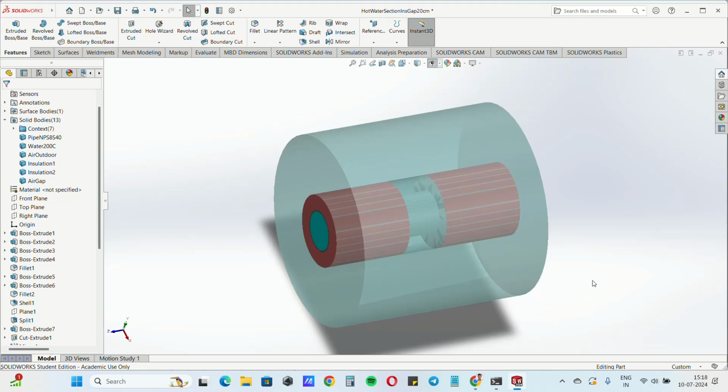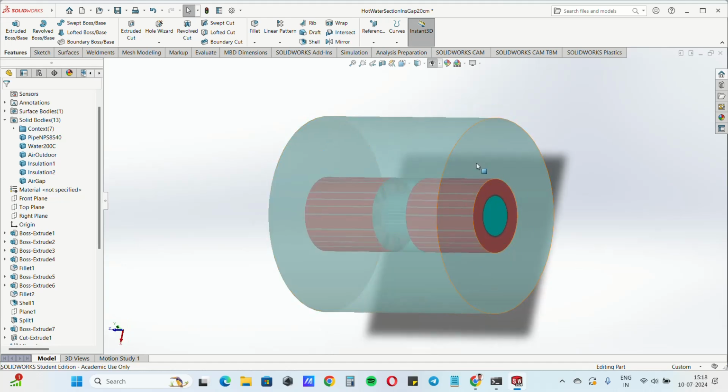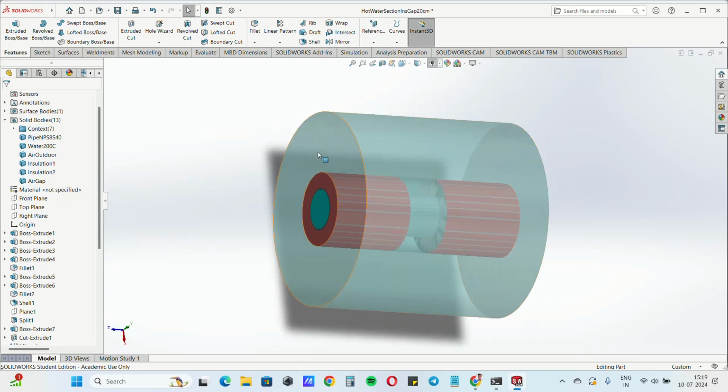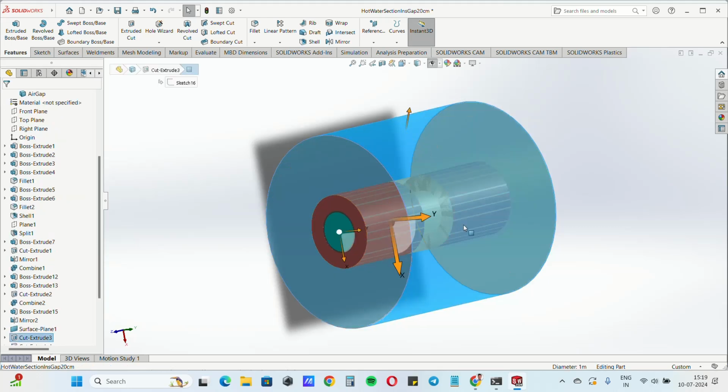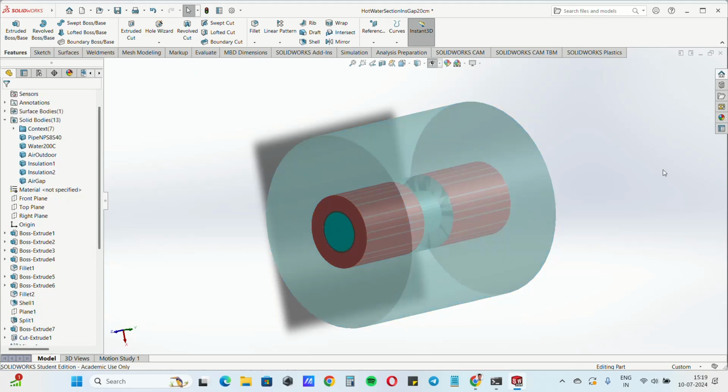With directed meshing we need 3 basic surfaces for each of the parts. We have 6 individual parts, and for each of them we need a source surface where we create a source mesh, a target surface to which we sweep the surface mesh, and the third surface, the guide surface, which is the outer surface of each part.